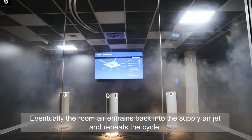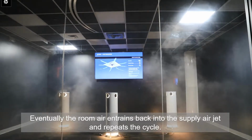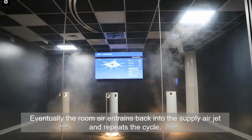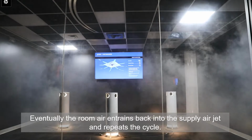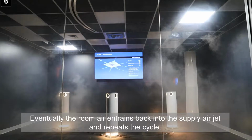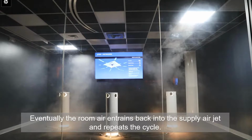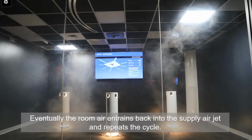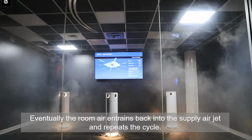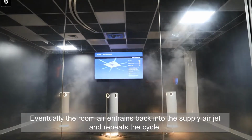Now, eventually, since we do have a high velocity airstream at the ceiling and a relatively low velocity within the room, that will create this air entrainment effect, where the air does eventually induce upwards and then recirculate back into that supply air jet. And you can almost see this curving arc motion. It's not a motion that we can readily predict, but this is the general trend of the air motion within the space for a mixed air system. It will induce back into that supply air jet, recirculate, and create our mixing action.